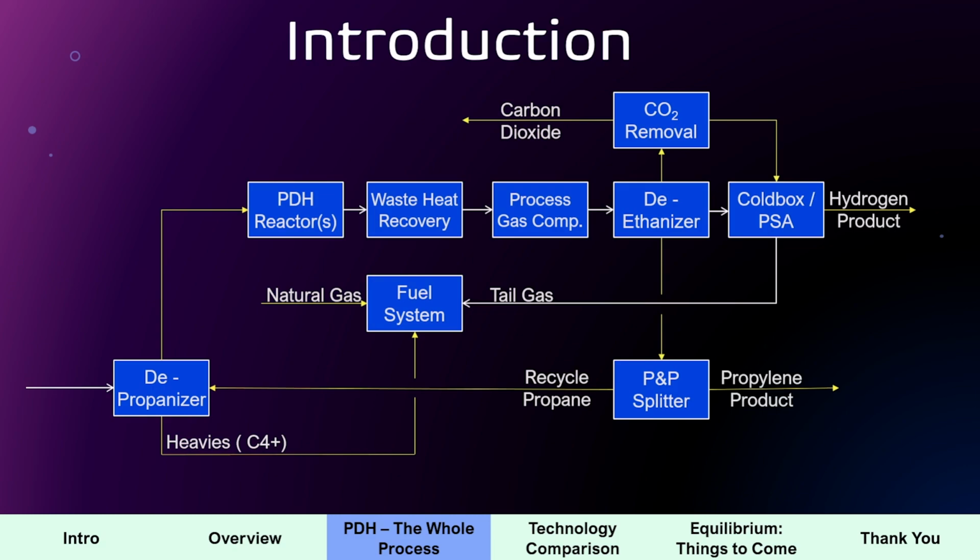There is a point where it starts turning from gas to solid. And one of the separation units we have uses a lot of aluminum heat exchangers, something like the cold box, which goes into very deep cryogenic temperatures. If solid CO2 were to form in these cases, it would cause huge damage and take that unit out of operation.